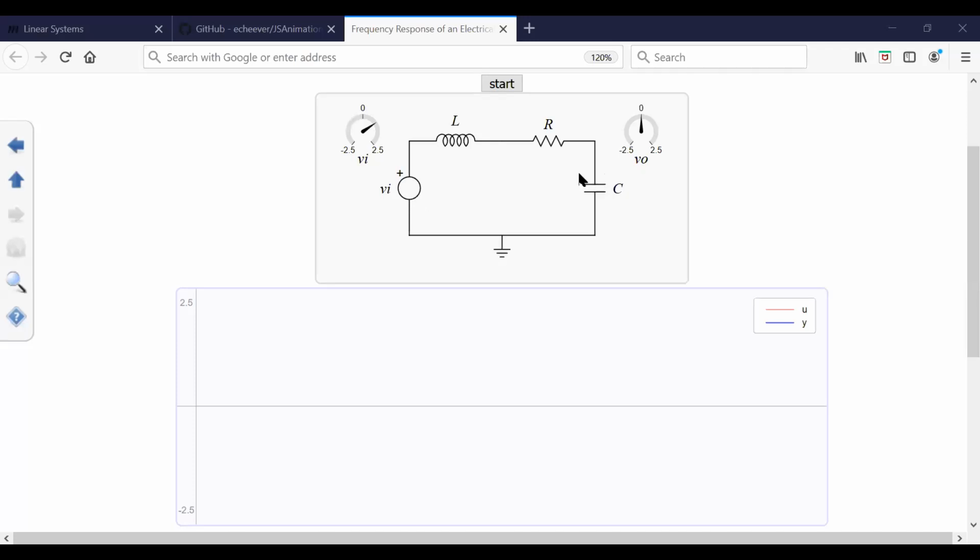So how do we do this simulation normally? We need to apply a sinusoidal input of varying frequency. In practice, the frequency response can be obtained by applying a sine wave input to the system, and we sweep the frequency from 0 to a value beyond the frequency range. The input is represented in red color, and the output will be in blue color. You can see what is happening here. The input will be a sinusoidal waveform of varying frequency.